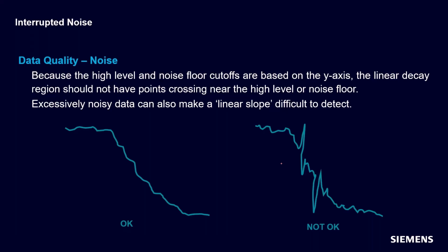So you might have to explore trying to improve the acoustic environment in that case, determining what exactly is causing these spikes in the data. For example, like on the previous slide, you might need to add diffusers into your reverberation room to get rid of those room mode locations, or you could also add some more microphones into that room to take more of a spatial average of the room when performing the measurement, and so on.